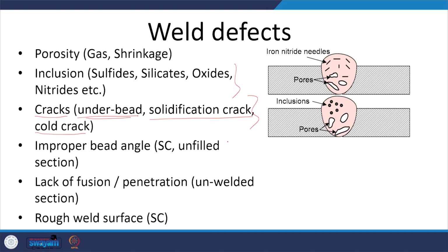All these occur due to an unfavorable welding procedure, including use of filler metal, use of proper preheat, and use of excessive restraint leading to the development of high residual stresses, or inclusions in the base metal itself leading to underbead cracking.